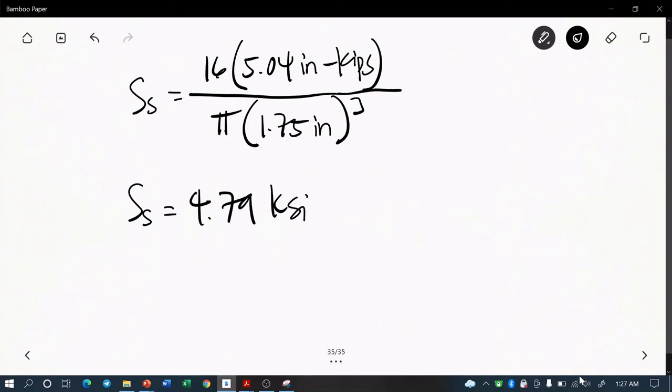We used that ratio, and thus we obtained the S sub ys. Then to S sub ys we applied the design factor in order to obtain the design stress. So that process is going to be reversed here in this requirement.